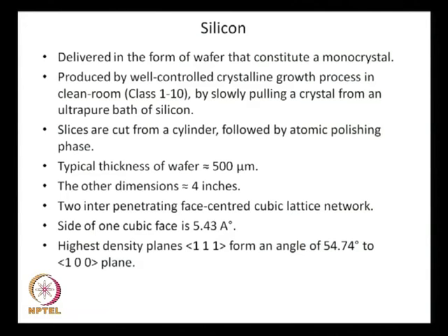All right. So, this is a particular feature which would be very important, because of the way the atoms are packed, when you take this silicon substrate for etching. After all, what is happening in etching? In etching, the silicon atom is reacting and the product is getting into the solution. So, if that plane is more packed with atoms, it would be more difficult to etch that plane, whereas, if some other plane is less packed with atoms, that plane will be easily etched. So, when it comes to the etching of silicon substrate, there would be an anisotropy developing within the silicon substrate.